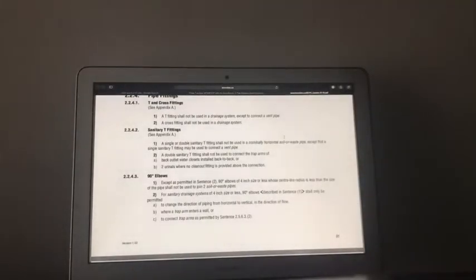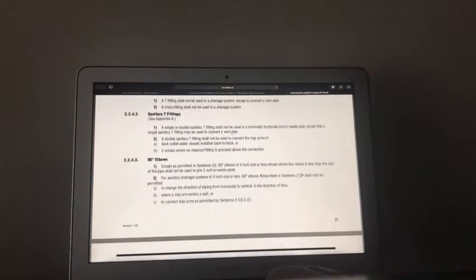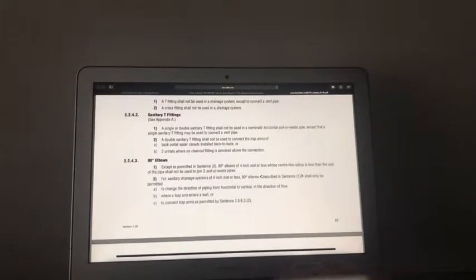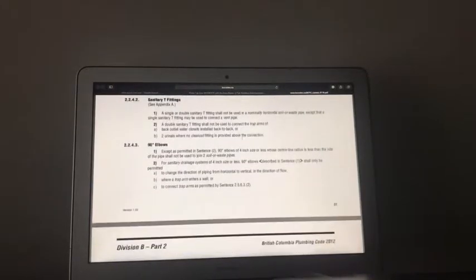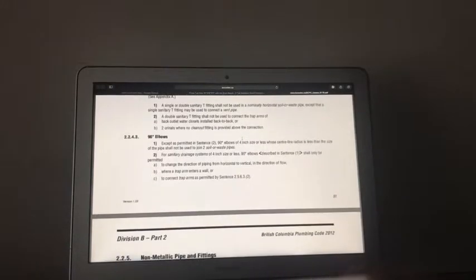No lavatory that's under 6 fixture units acting as a relief vent for your circuit vent. You cannot do that. You can only pick up dry vent with that kind of connection. And just to comment on vents, they're getting pretty strict. They don't want anybody coming off horizontal to connect a vent underneath the ground for your groundworks. Traditionally, he only let me get away with it on an interceptor, but not for sanitary.